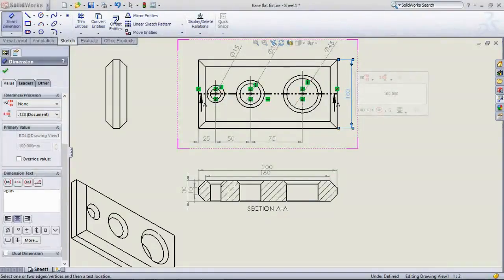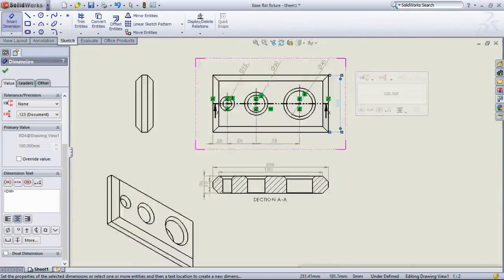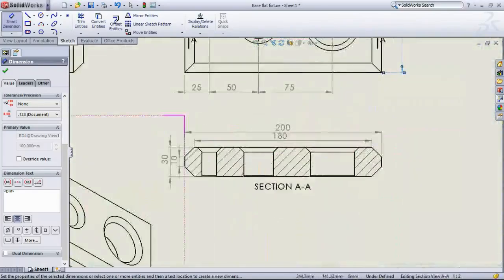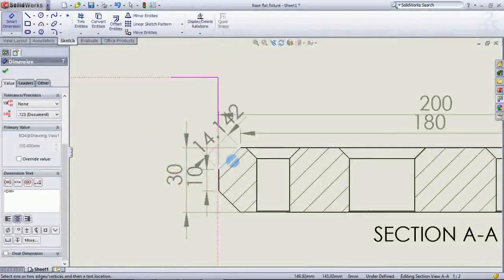Yes, as I have shown here. I think now the drawing is finished. I just missed one dimension here for showing the chamfering details. Just mention which line, and mention the degree of the chamfer cut. So he will turn the rotating bench vise, fix it at a 45-degree angle, and give a longitudinal milling cut. Then he can finish this chamfer.